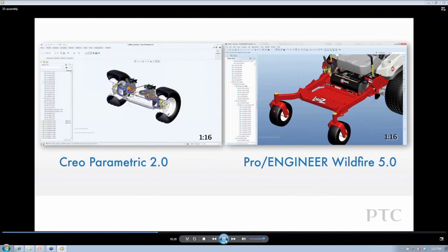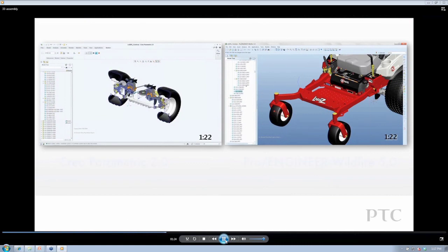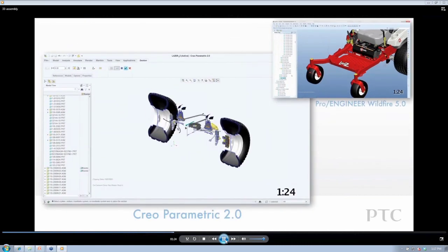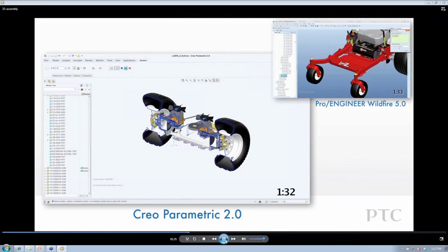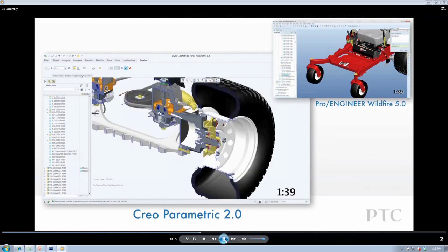And then also one of the new enhancements in Creo is 3D sectioning, which is dynamic sectioning. You can see you can make a plane or use one of the default planes and then go ahead and dynamically drag it around. The section tool allows you to control the hatching, so you can see very clearly what the hatching is. You can also modify the hatching.